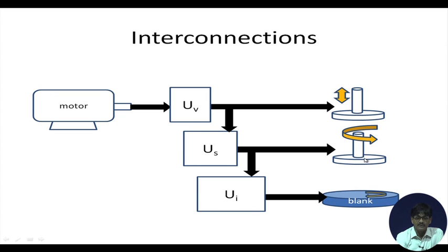but in addition they are moving fast against each other, so that the circumferential movement they suffer per stroke has changed. Why? Because the strokes per minute have remained constant, while the millimeters of circumferential movement per minute has changed. If that increases, therefore, millimeters of circumferential movement per stroke, equal to the feed, that will become higher.